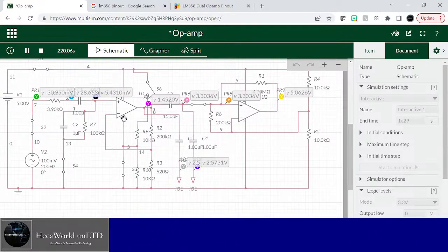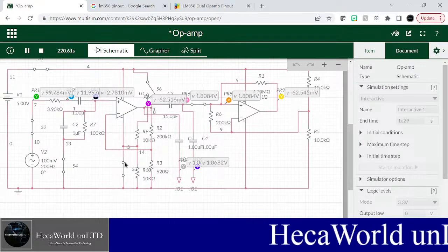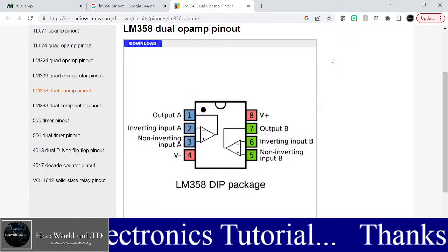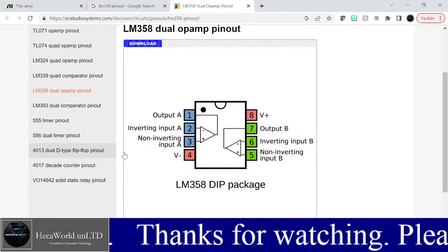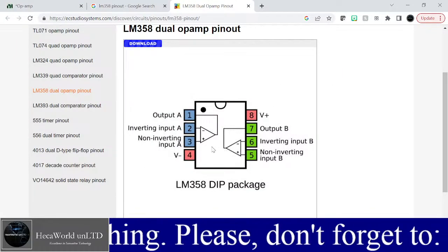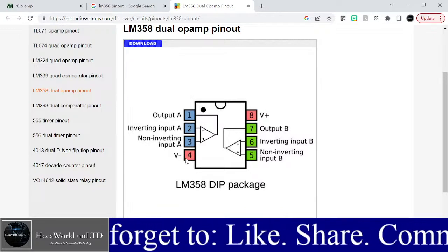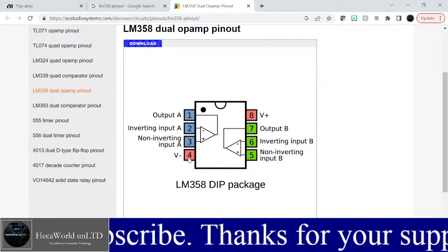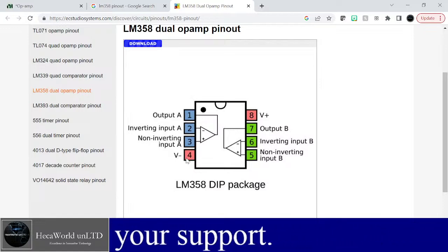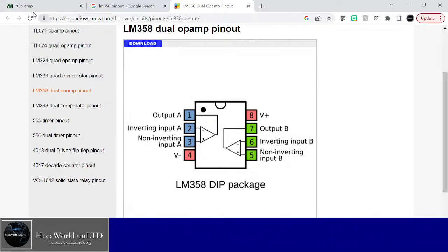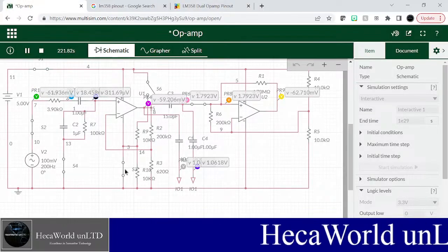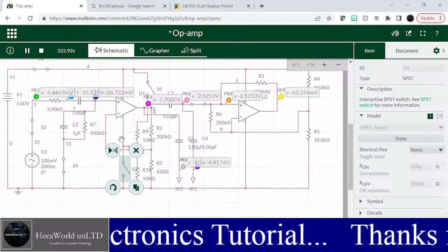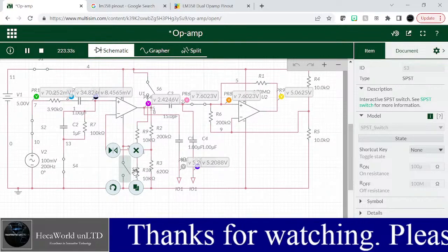So what we did was we pulled this pin 4, let's go back to the pin out. As you can see, pin 4 is the ground pin, the negative pin. So instead of leaving it as the negative pin, we put it on a virtual earth. We created a virtual earth. This is what we did. We removed it from earth, so that's why we put it open, and put a switch so we can just turn it off.